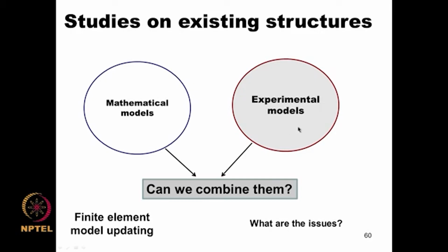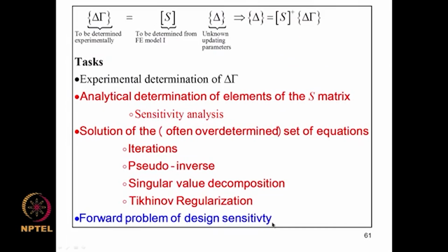we have experimental tools becoming available to us, and thus we can measure the performance of the structure under either diagnostic loads or operational loads. So the predictions in these situations from an experimental model and a mathematical model often do not agree, and the question is how do we update the mathematical model to reconcile these two predictions. This leads to the topic of finite element model updating, and we briefly reviewed the issues related to this question and developed specifically one approach that was based on so called inverse sensitivity analysis.